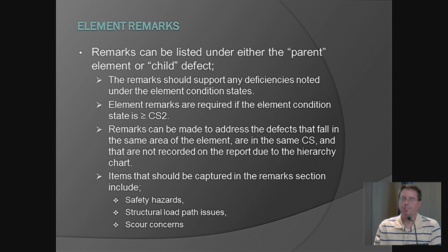Some of the items that should be captured in those remark sections are if there are additional safety hazards, if they notice load path issues, and scour concerns.